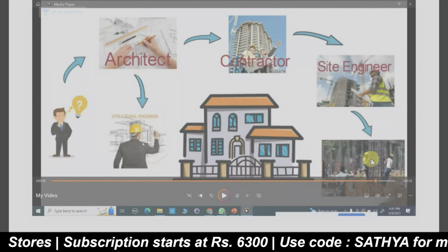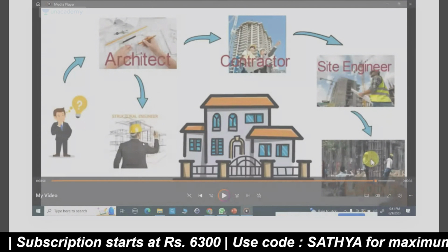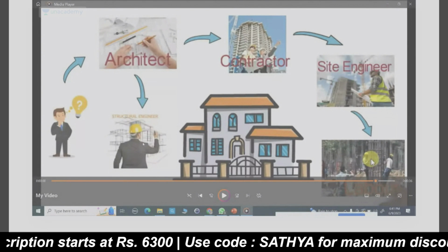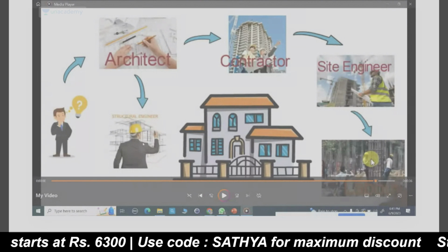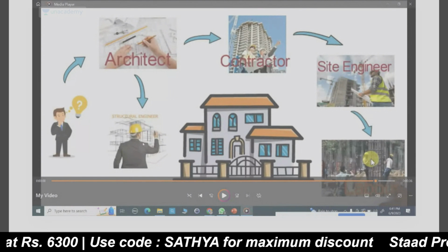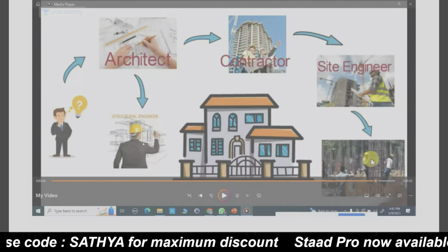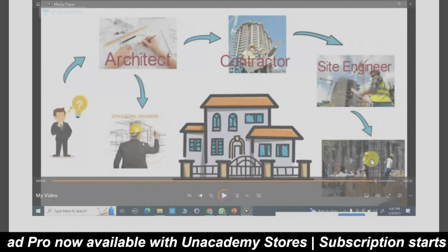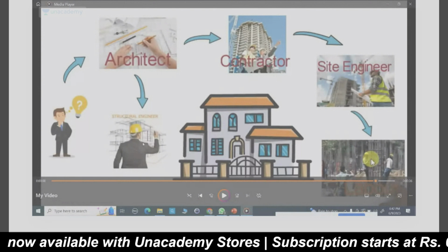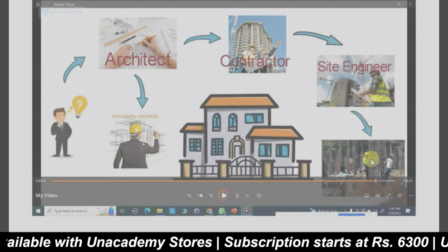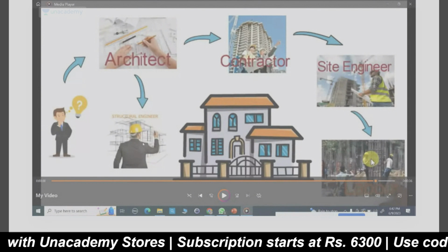All that comes under the architectural drawing, the aesthetic view. Whereas the structural drawing includes the skeleton of the structure, how the structure needs to be supported according to the architectural elevation, like the column location, beam layout, slab layout. Everything will come in the structural drawing.